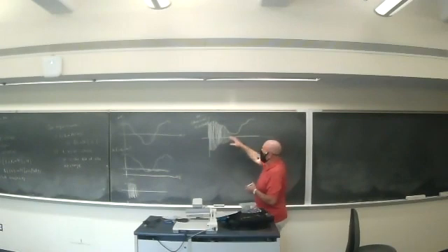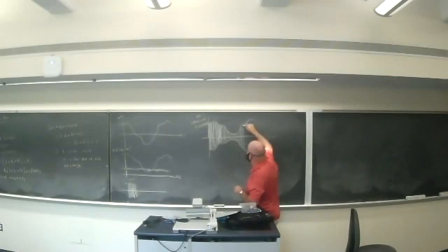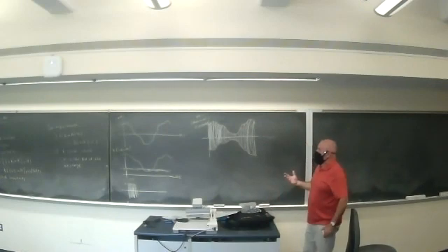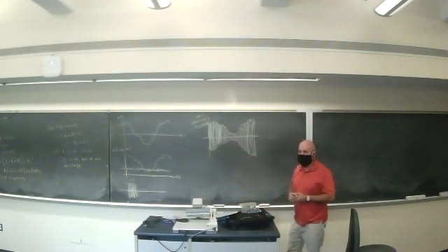Okay, so if you zoomed in on this, you wouldn't see this line here that's my message. All you'd see is this high frequency cosine, but the amplitude of that is changing. So this is the actual AM waveform that I'm sketching now. But if you look at that, you can say, I still see my low frequency message in there, right? It's shifted up, but I see a representation of that low frequency message.